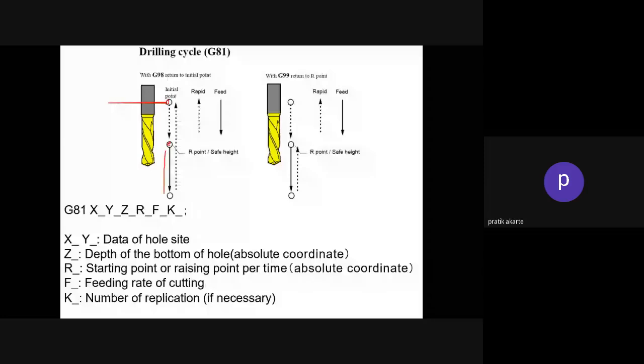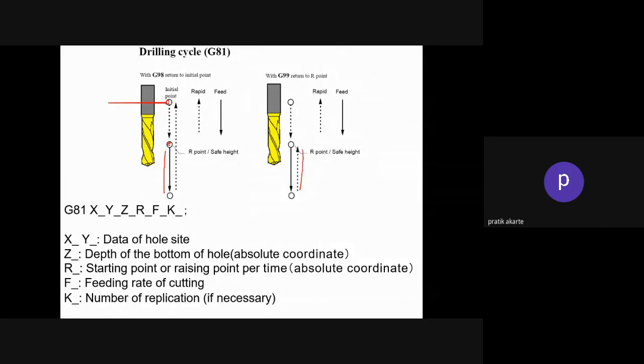After that, once the hole is drilled, the tool stops rotating. It is retracted to the safe point, and then moved to the next point. Again the same procedure.